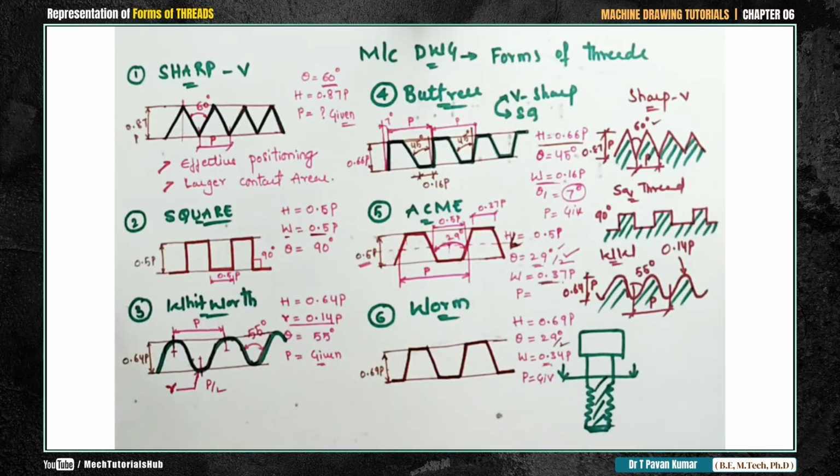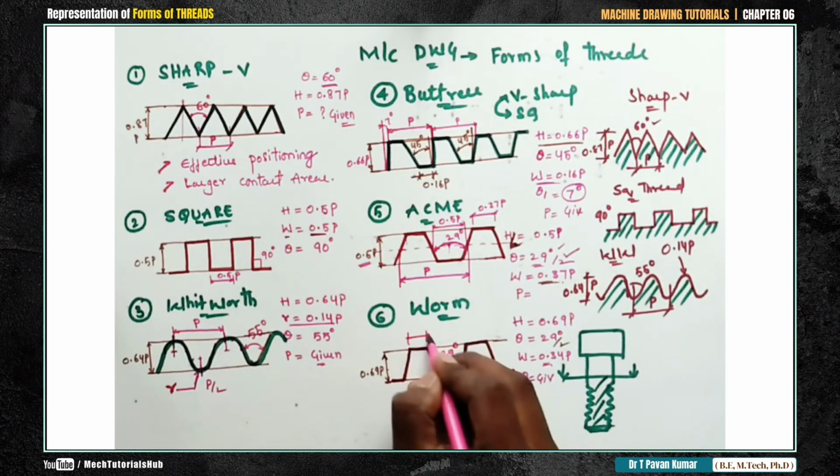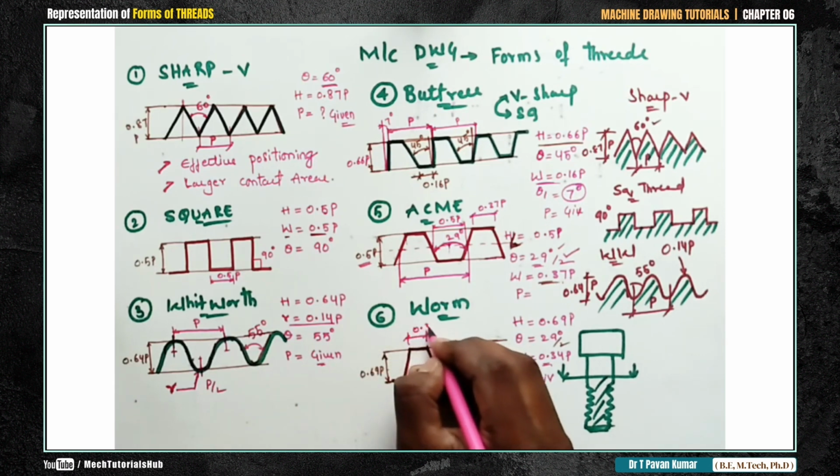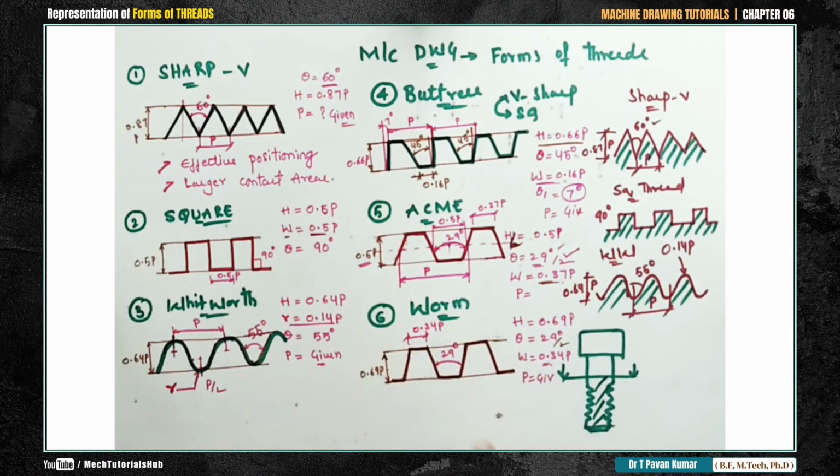Other than this, now as I said initially, it is a cut section. Once you cut the model, you could see all the profiles of this kind. So if you cut the model, you need to hatch the model, that is also important, okay. So how to hatch the model? Simply maintaining 45 degrees inclination with an offset distance of 2 mm, okay.